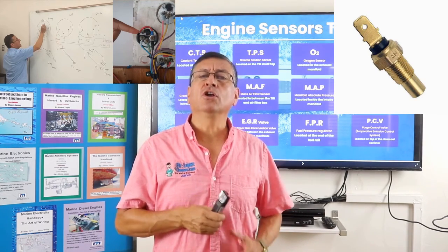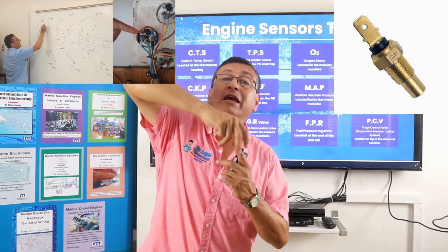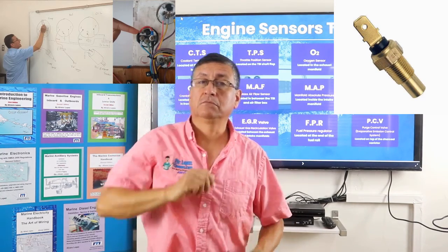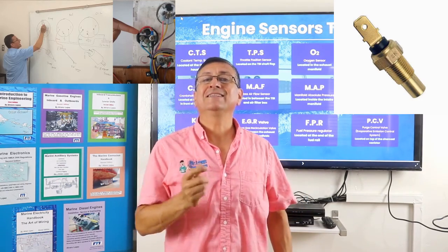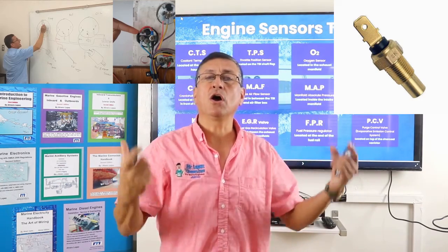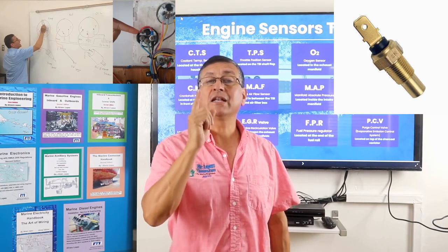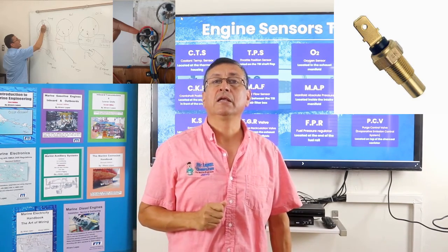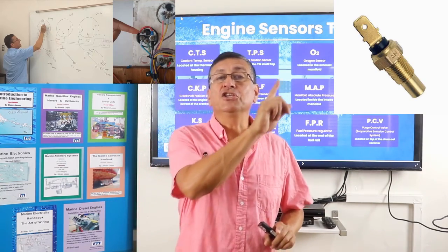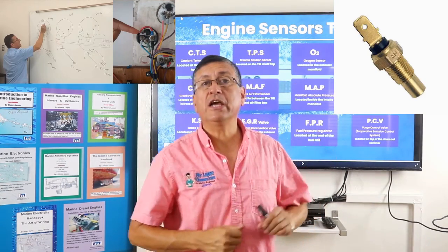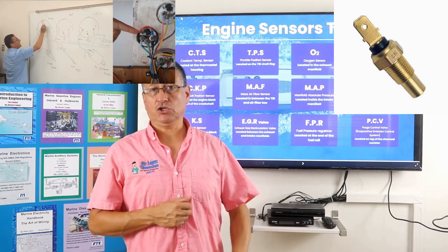And what about the ground? The ground is because those sensors are bolted on the thermostat housing or on the oil bracket. This is the ground. The ground is with the block of the engine. Those are the sensors with only one terminal. Normally those sensors are dedicated to the gauge, oil pressure gauge or temperature gauge.